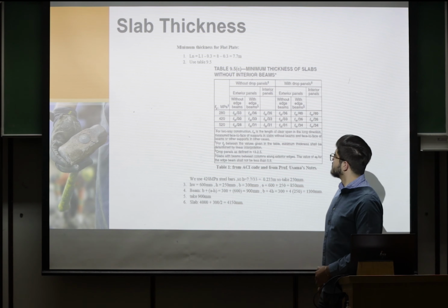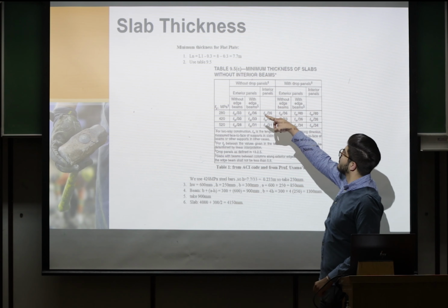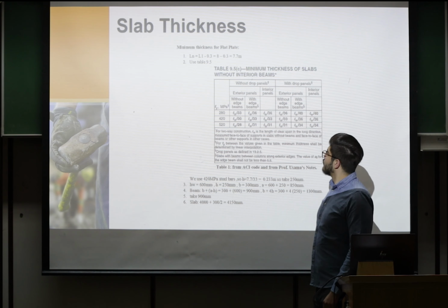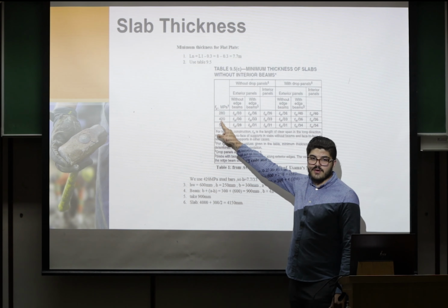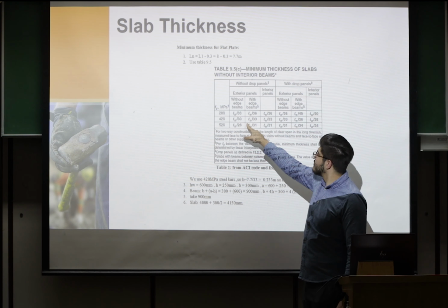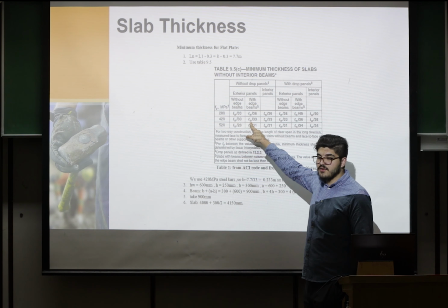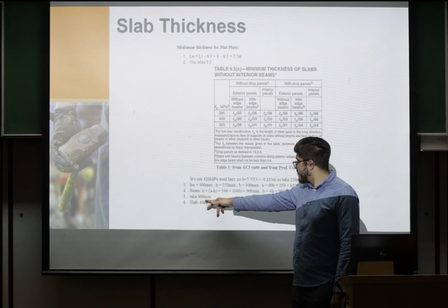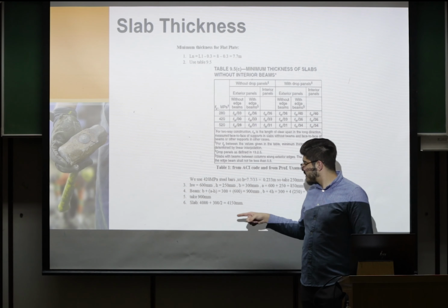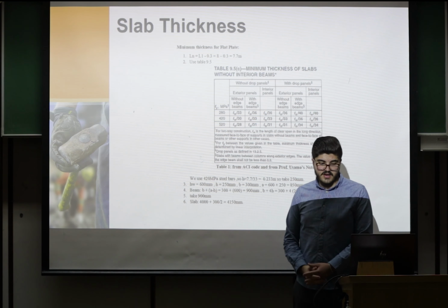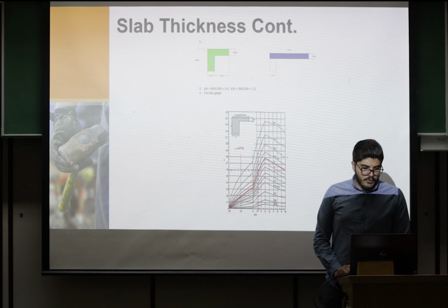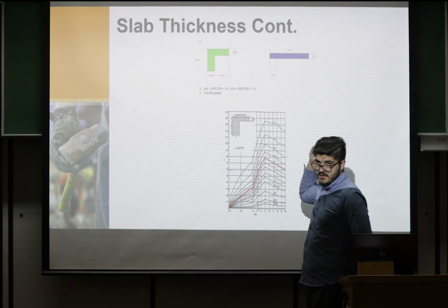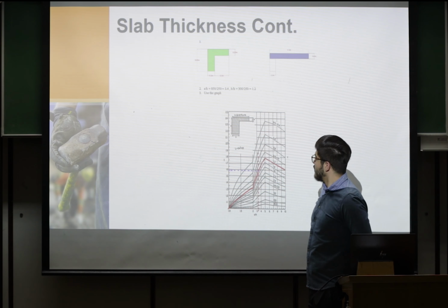slab thickness. So first of all, we have Ln, which is L1 minus 0.3. We found that it is 7.7. When we go over here, we choose 420, and it is with edge beam, so we use Ln over 33 as per the ACI code. We did the procedure, and we had to take 900 millimeter. Then for the slab, it was 4,150 millimeter.